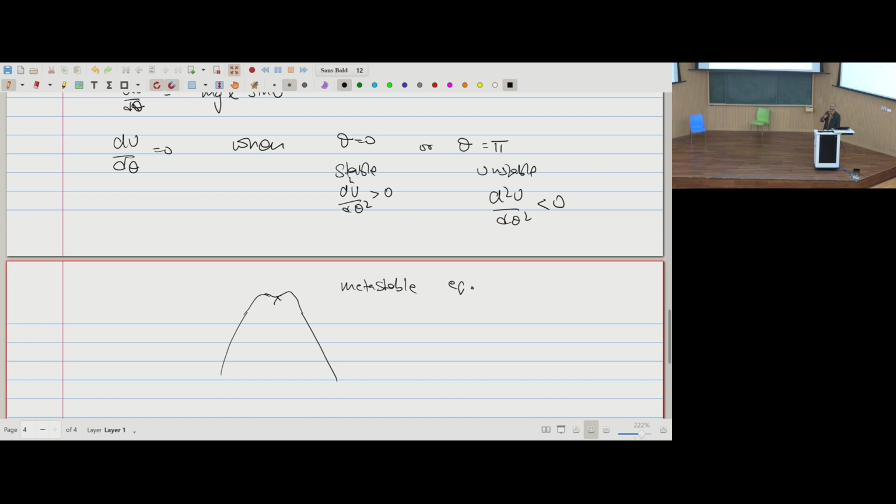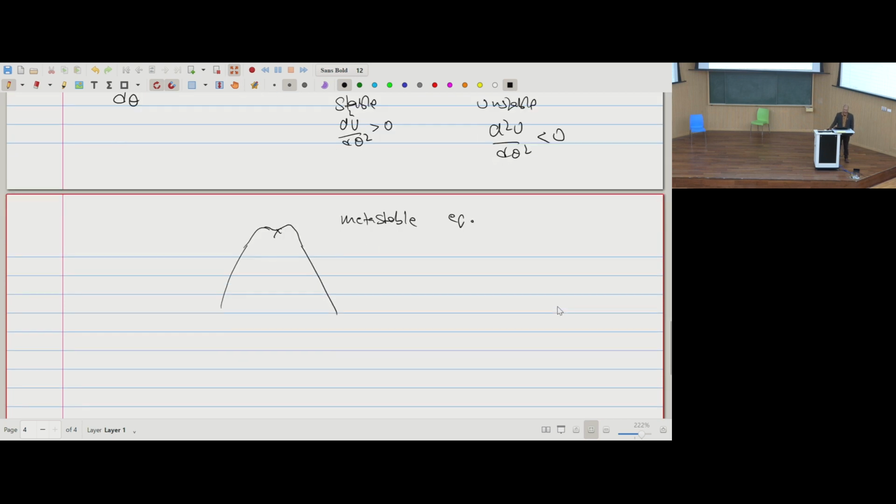So when you're designing a ship, for example, it may seem that I've done an experiment, I give it a slight push, it stays stable. But if you go into a storm where the push is not that slight, you will see the system was actually metastable, then it will topple for a large push. Okay? So these are called metastable systems. And you also have a neutral equilibrium.